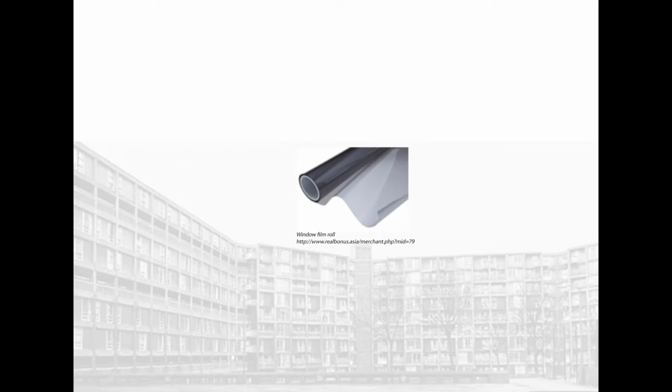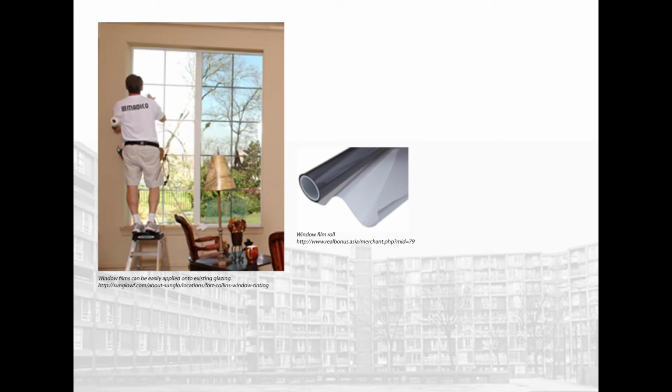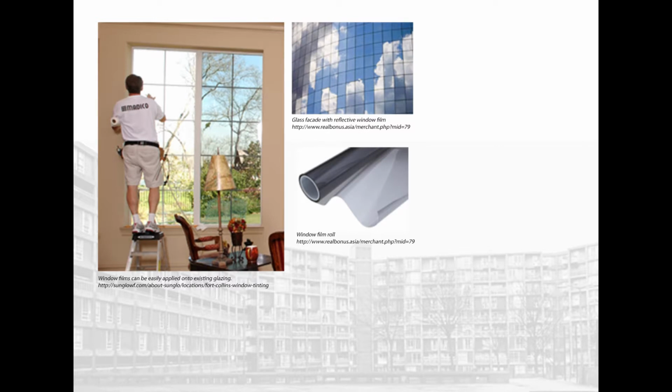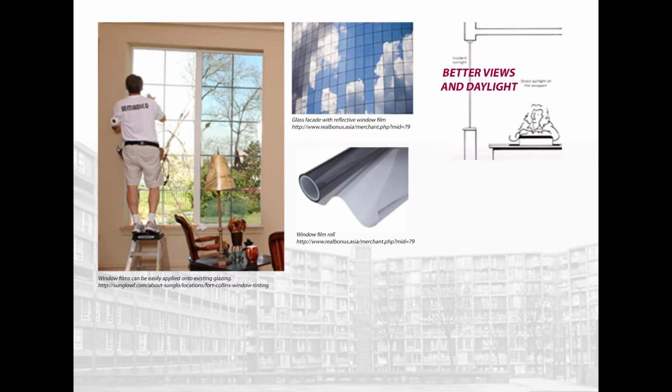Window films are a low-cost retrofit option which can be applied on the interior and exterior of glazing, although exterior films tend to be better at preventing overheating but is less durable. However, both types of films can also act as a shatterproofing feature as well as reducing glare and reflecting in sunlight.